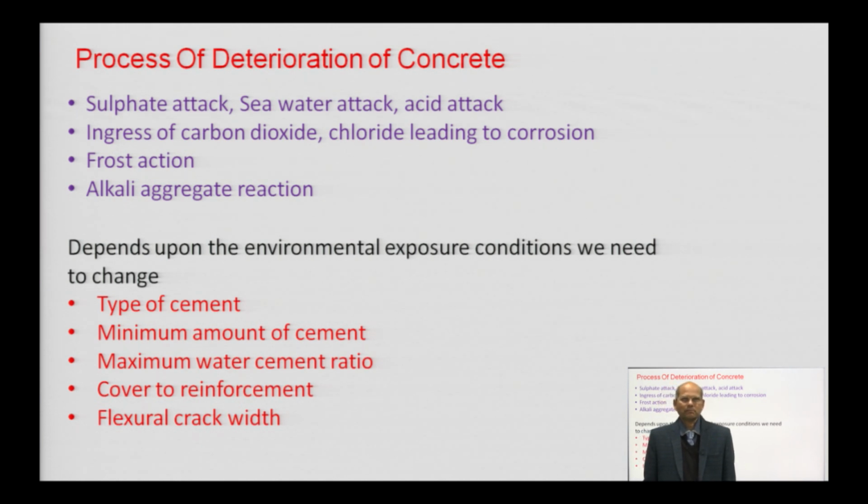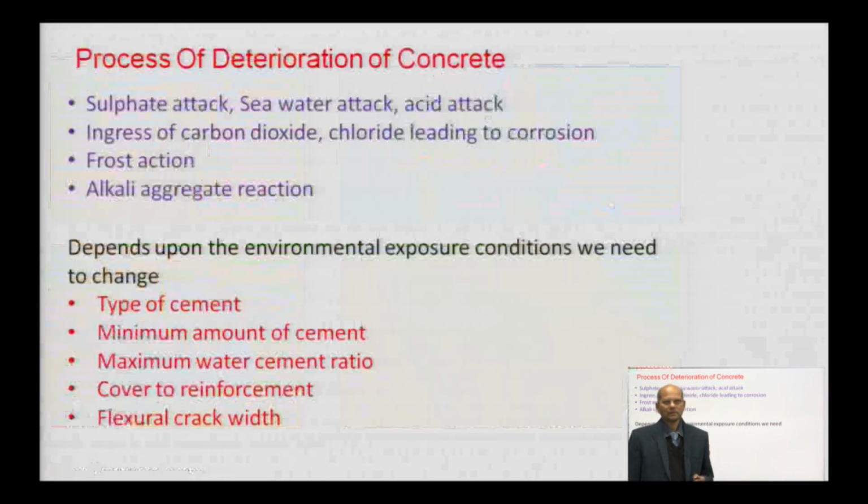And similarly, we have to restrict the maximum water cement ratio, because once water increases, after the evaporation the capillary pores will be more. Then cover to reinforcement: if cover is more, certainly ingress of deleterious material will take time to reach that position. Then there is a restriction on crack width in fracture. So, all these things we have to consider for durable design.